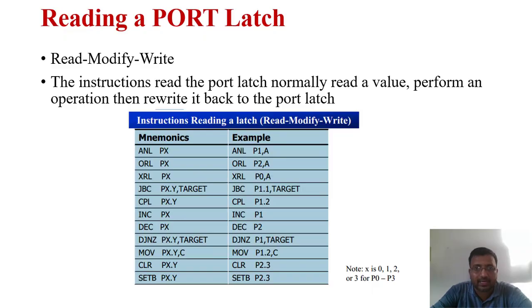Next we can see read, modify, and write. For that we can use different instructions, and I'm going to elaborate those particular instructions. Reading a port as a latch: the instructions read the port latch normally, read the values, perform an operation, and then rewrite it back. Also we can rewrite it back to the port latch.